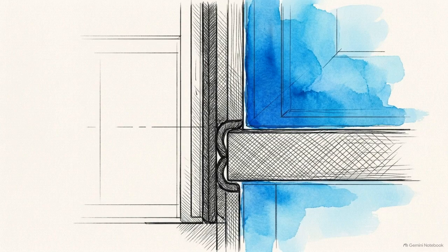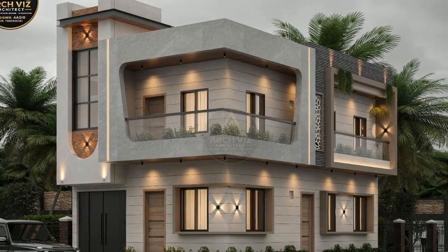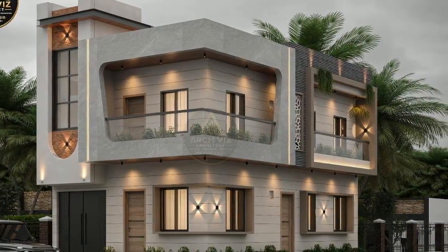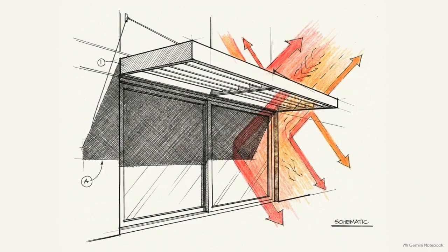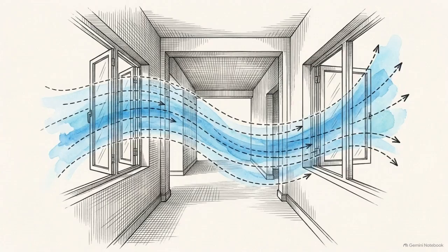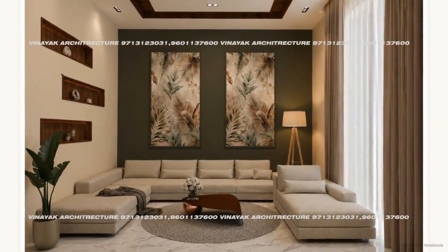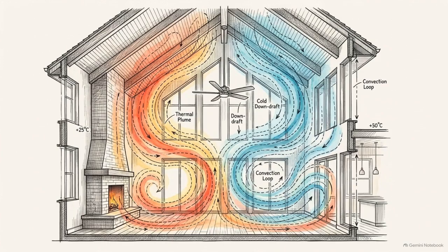The home's exterior envelope acts as a massive thermal battery, continuously absorbing and trapping solar radiation throughout the day. Intercepting that heat before it enters the living space requires architectural defenses like external window shading, proper directional orientation, and strategic cross-ventilation. Once inside, the interior volume of a room establishes the baseline workload. High ceilings and open floor plans dictate exactly how hard any appliance must work to achieve a comfortable temperature.